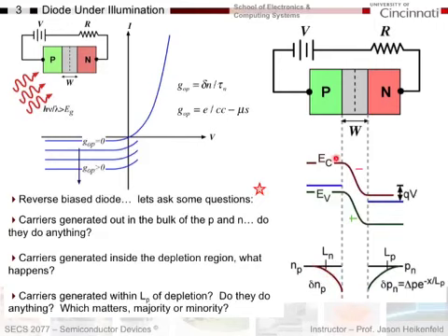Meaning that every minority carrier electron that's generated thermally, we said previously, if it's close enough, it's going to fall off the cliff edge. It is created thermally, it wiggles around, and it falls off the cliff edge. And then way out here, it's too far from the edge to make it there, right? And so that's why we had this profile showing that if you're within a diffusion length of the edge of the depletion region, here's the depletion region, then the electron concentration goes down because these electrons are basically falling off the cliff.